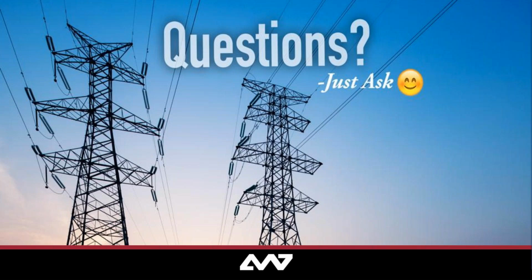And as far as multiple connections, if an outstation supports multiple masters connecting to it, it can still listen on just a single port number like 20,000 and can accept connections from multiple devices on that port number. Or it could choose to use 3 different port numbers if that was desired. So either way works. Routing is done for you even if you use the same port number. But it depends on the outstation, what it supports. That is a key point.